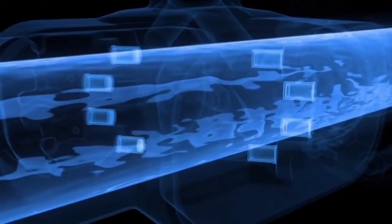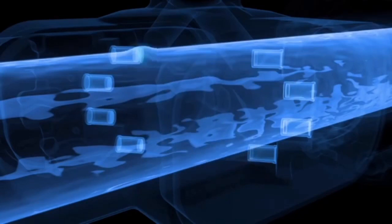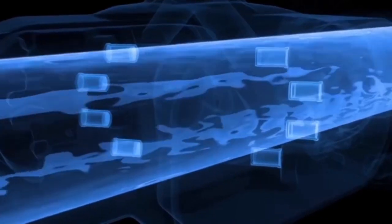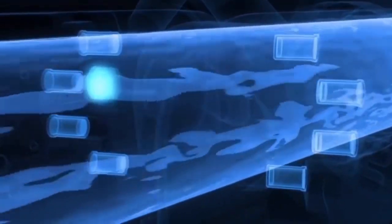By increasing the number of sensor pairs, it is possible to accurately detect and mathematically compensate for flow profile distortions over the entire pipe cross-section. When there is no flow, the signal transit times are the same upstream and downstream. Once the fluid starts to flow in the measuring tube, the ultrasonic signals are accelerated in the direction of the flow and decelerated against the flow.